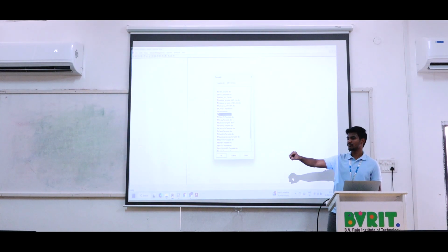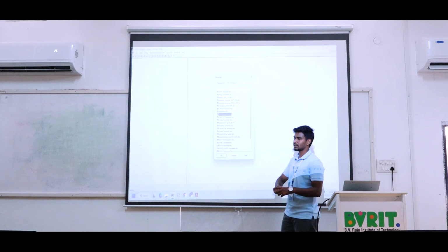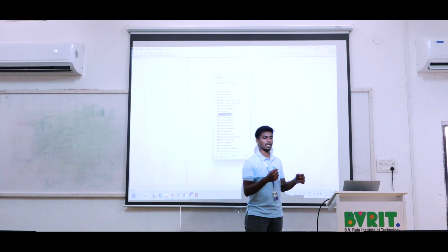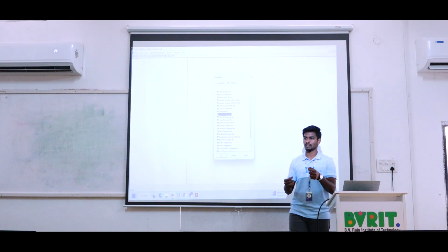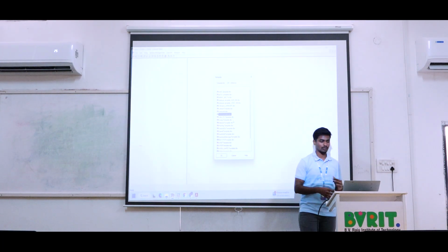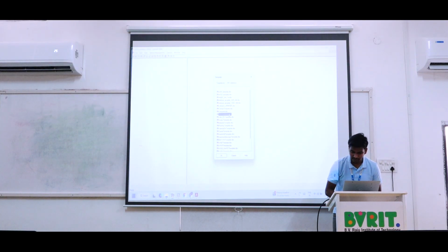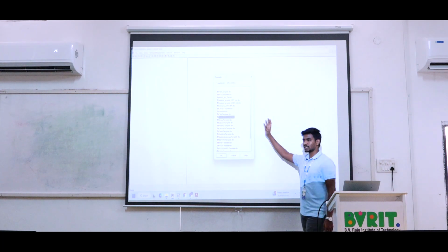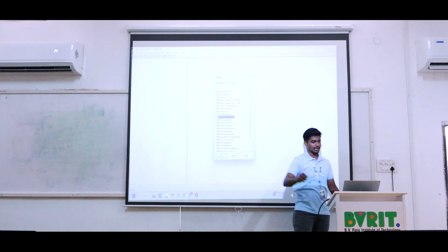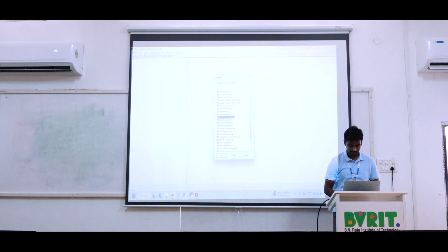Then, initially you were asking about the MDC, sir. The MDC is nothing but the multi-network database. In the MDC file we can store a multi-network collection of FlexRay, Ethernet, J1939, those kinds of things. But here we are going to work with the CAN template. One more template is the CAN FD template. The CAN FD template is for the fully extended format only. So we are not going to work with CAN FD; we are just going with classical CAN.